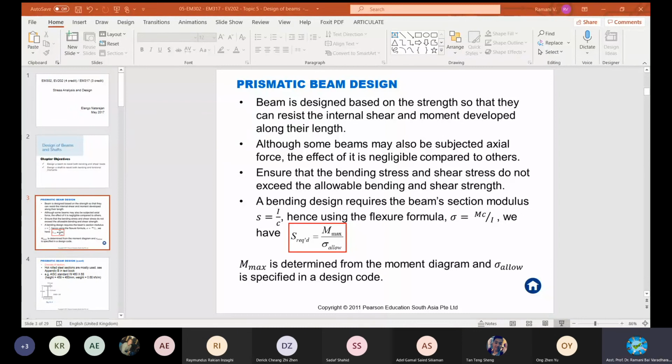So the maximum allowable will be like last time, when we used a factor of safety of 1.5. You can still follow 1.5 as a factor of safety for the shear stress and also for the normal stress. Okay, coming to the adequacy of the fasteners, I will explain about this one in the next class. While doing the calculation itself, I will explain how to determine the allowable and the applied or required values.